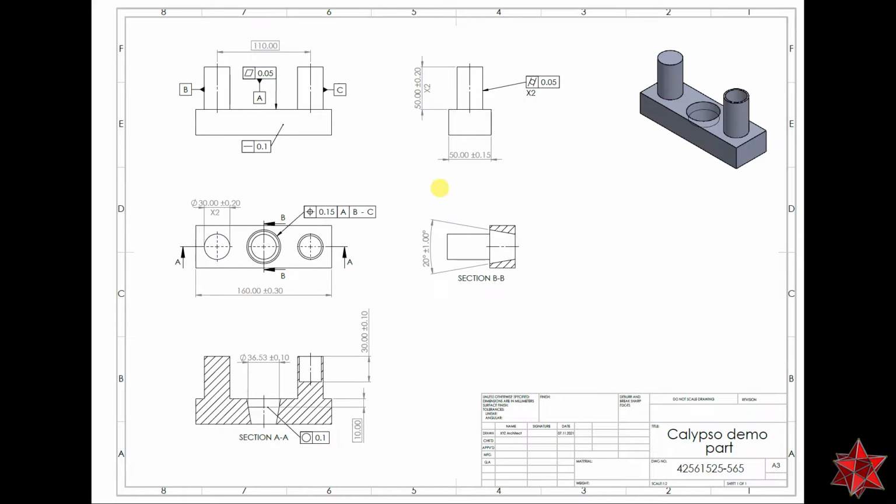When you first look at the drawing and you want to start creating a program, you must first look for the datums, right? But how do you look for the datums? Because as you know, these are the datums, but you can look at them and say, okay, so how do I do it? I do it BAC or CAB, or how do I do it? No, this is the tolerance reference frame, the only one that we have in this drawing. So we will use this reference frame to construct our alignment.